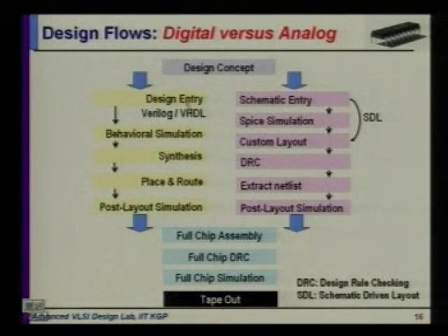There we typically enter the design in a high level language, and the popular languages today are Verilog and VHDL. And then from there we do a behavioral simulation. When you enter the circuit in this language, you can simulate that circuit, right? What is this behavioral simulation? For example, you want to design a processor. You will enter the design at a level which is called register transfer level, and then you will do behavioral simulation of that register transfer level code using simulators.